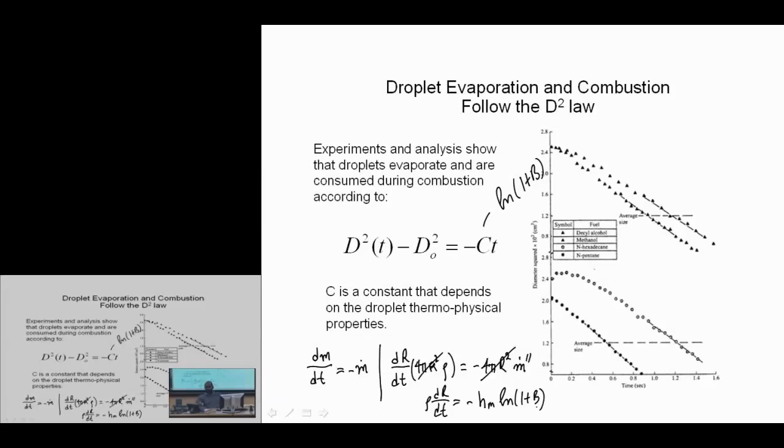and so where the r of t issue comes in is that to get the d-squared law, for droplets like this, the Nusselt number is equal to h times a characteristic dimension over thermal conductivity, and for a small droplet, for example, this is a function of the Reynolds number and the Prandtl number, but for a small droplet, this is equal to 2.